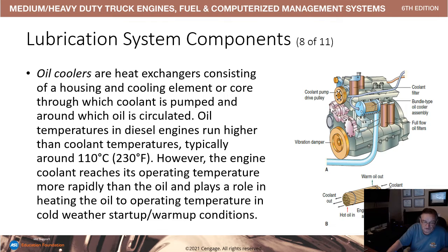Oil temperatures in diesel engines run higher than coolant temperatures, typically 230 degrees Fahrenheit. However, the engine coolant reaches its operating temperature more rapidly than oil and plays a role in heating the oil to operating temperature in cold weather startup and warm-up conditions. This is considered a bundle, and a bundle engine oil cooler is considered the most efficient.